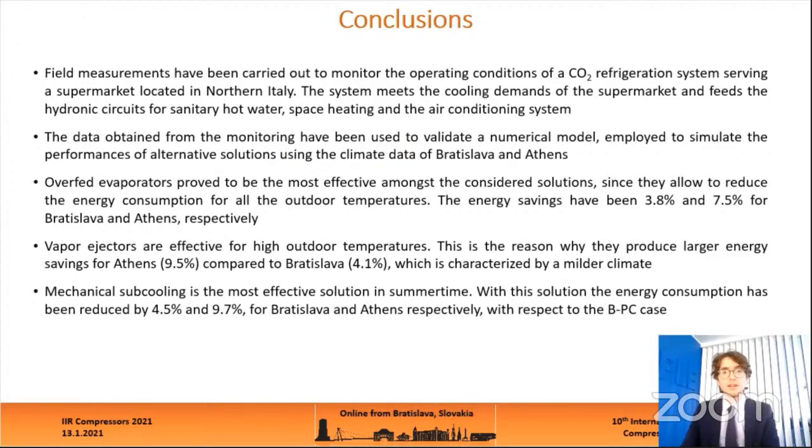The data obtained from the monitoring have been used to validate a numerical model and simulate the performances of alternative solutions using the climate data of Bratislava and Athens. Overfed evaporators proved to be the most effective solution since they allow to reduce the energy consumption for all the outdoor temperatures, with energy savings of 3.8% and 7.5% for Bratislava and Athens respectively.